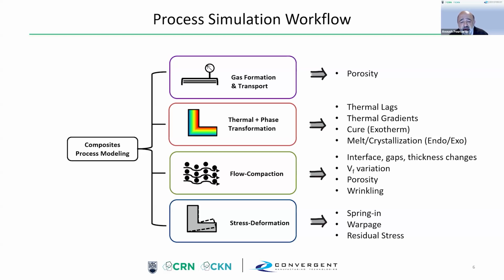Based on that, we get material properties that allow us to understand how the material will flow, how it'll compact. If it's a weld, how the weld will heal and cease to be a defect. And then once the material solidifies, because you're cured or because you go cold again, you start developing stresses which lead to process-induced deformation, or if they're locked in, give you residual stresses that affect your mechanical performance.